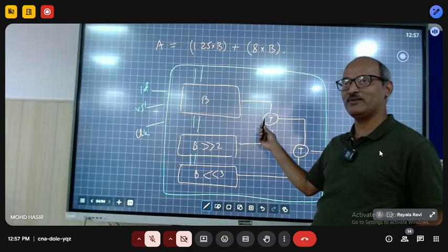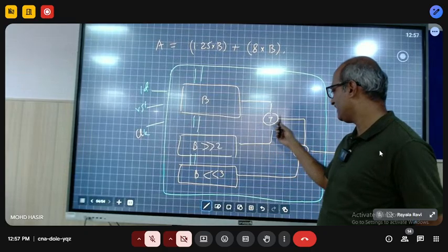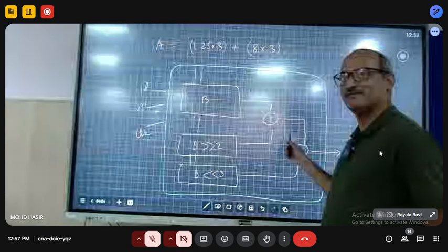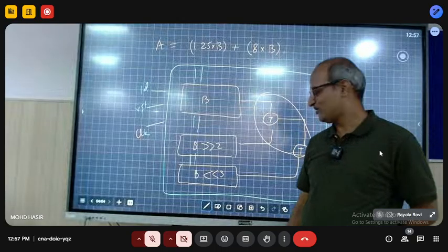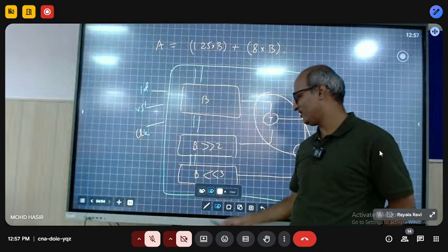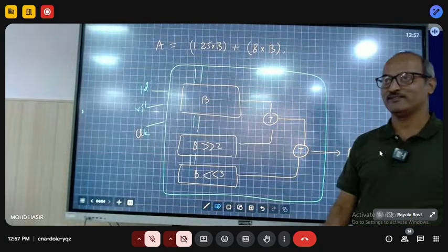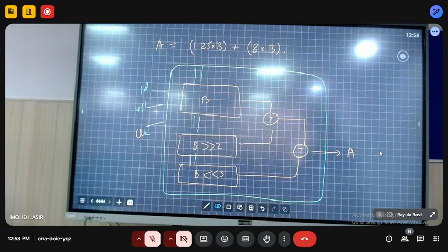This is the RTL of your design, right? And then, because now we are doing shifting, there will be clock, reset, okay, load, because you need to load this value. While you are loading this value, it should get copied into this too, right? So there will be some load signal, a reset signal, then a clock signal.